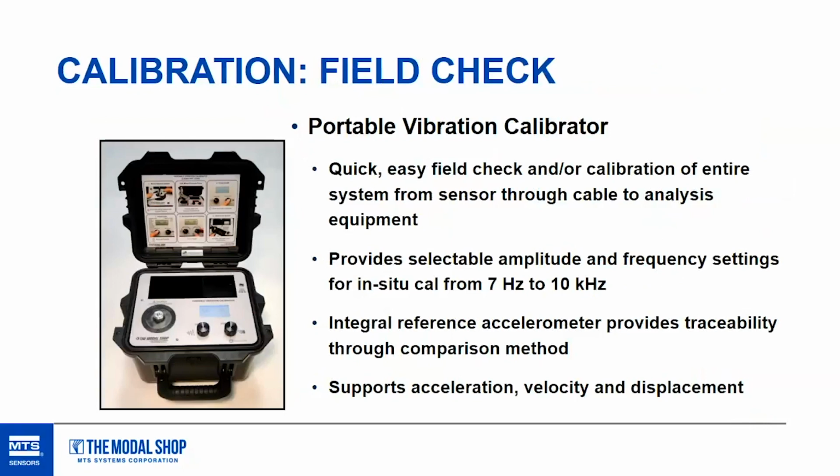A simple version of this is often used in the industrial world where you're doing condition monitoring on a pump or a motor, something that is vibrating that you want to make sure is not vibrating too hard, is not having a component failure. You can look at maintenance intervals for these type of heavy equipments to see if you need to change out a bearing or something in the system. And monitoring acceleration over time is a good way to do that.